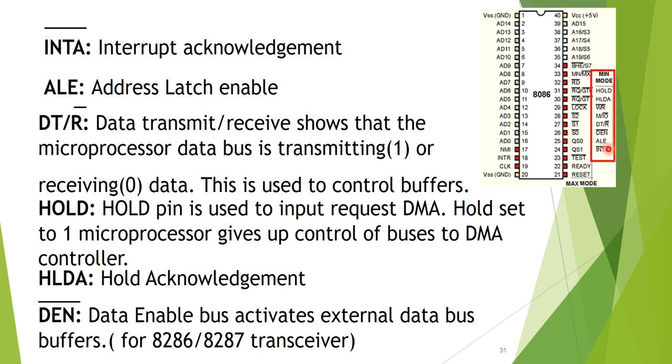Then we have the ALE, that is the address latch enable. It is used to latch the AD0 to AD15 address/data bus in the external latch. That means by this latch we separate the multiplexed bus, so it is used to demultiplex that bus.